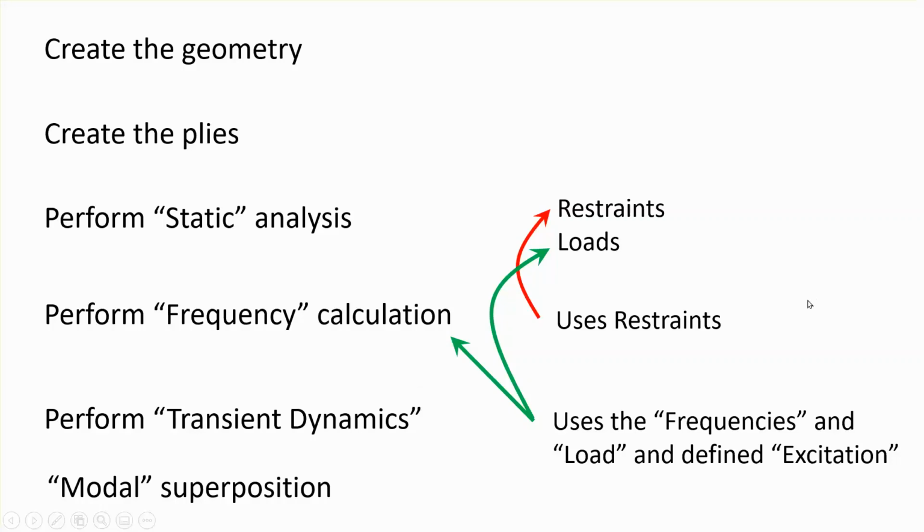So CATIA's native FEA solver really cannot handle nonlinear dynamic problems. It's based on modal superposition and therefore linear dynamic analysis.